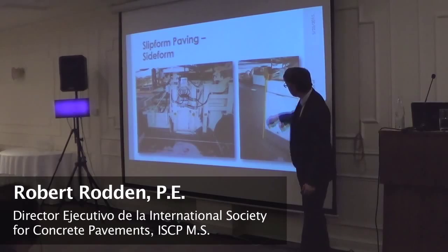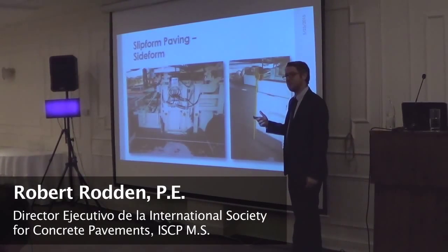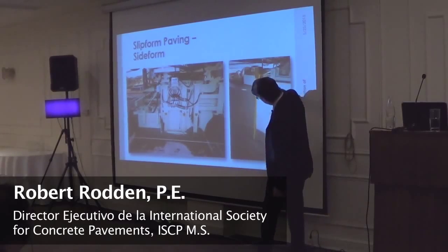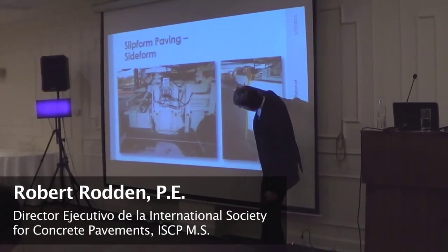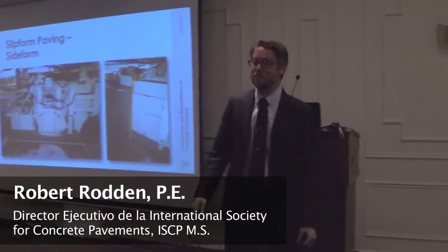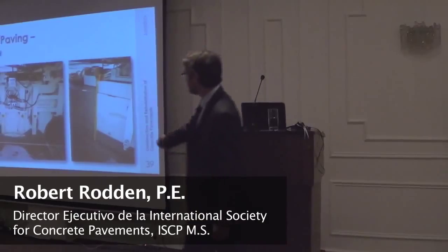If you look close at this photo, you can see one perspective of that edge slump. So remember, we're building it up taller than it needs to be. You can see that perspective is a constant angle. This one kind of curves down to approach what it needed to be. I've got another photo that shows more of that edge slump in action, but that's right behind the pan.